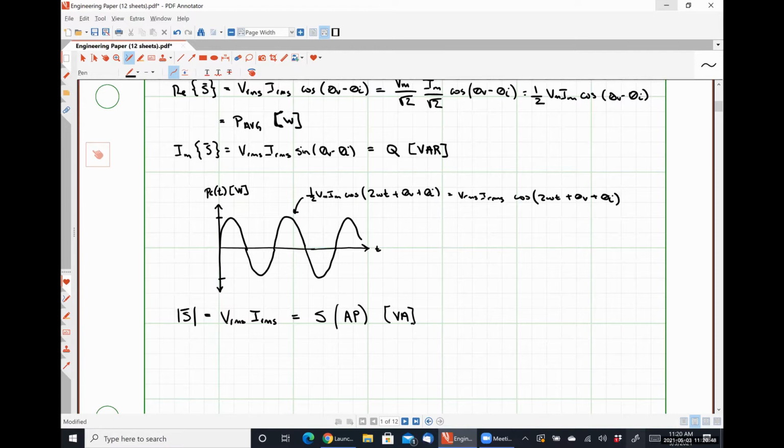I'm getting away from my original point. Whenever you're setting up or choosing the type of wire in a home, in a circuit, or anything like that, it's always based on the apparent power, because the apparent power tells you the absolute maximum that the current will ever be, because it doesn't take into account phase differences or anything like that that would cause things to cancel each other out. So when you design electrical systems, you're always designing to apparent power specifications, okay? Because that is the absolute worst case scenario bundled up into a nice, neat little number. All right.